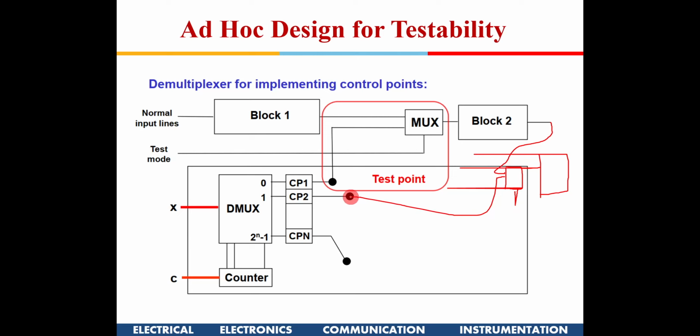So this can come from the second here, right? Similarly, because each block needs some test vector to be given, right? So now this is the test vector. This is only a single pin catered for to provide the test vector. So how to route this particular pin to different blocks? This mux is only routing the test vector or the previous block output here, but this test vector itself needs to be routed to different blocks, right?